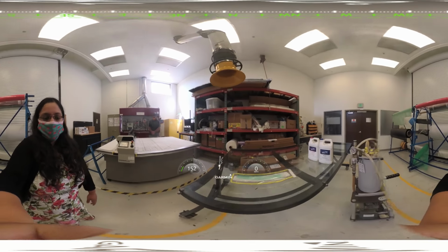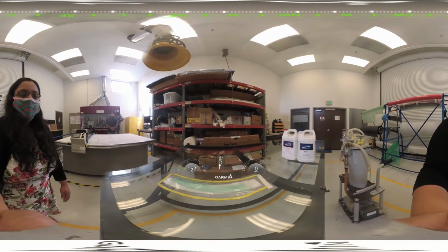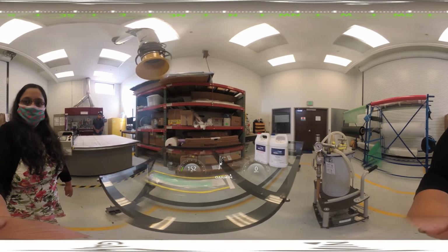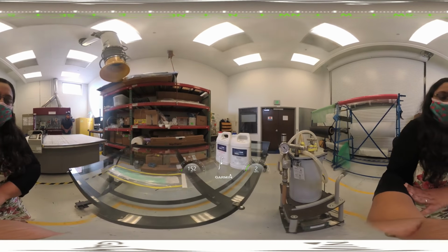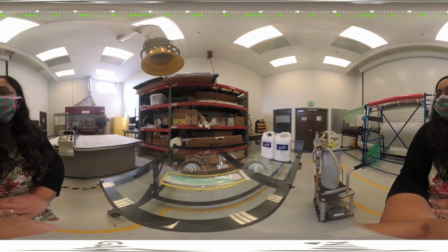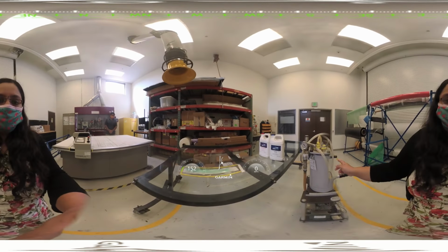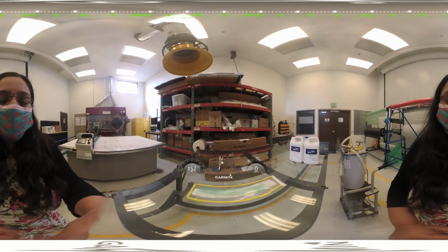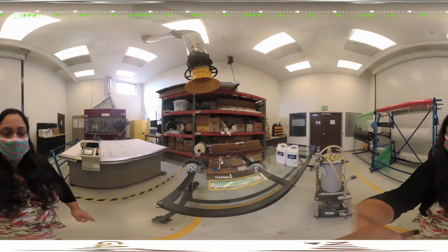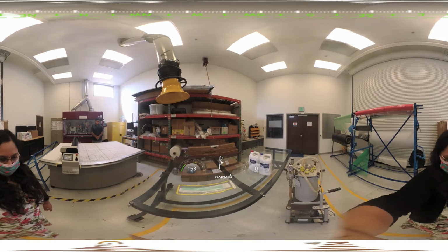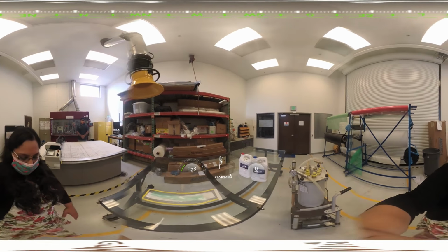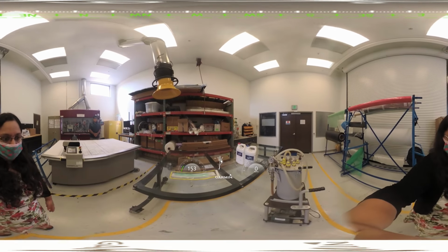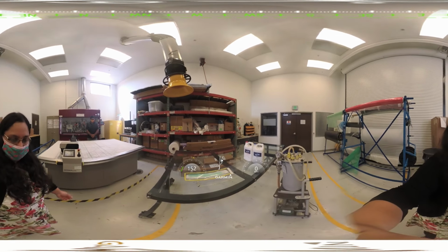And then the fabric is laid up in different number of layers, 6 or 8, and the resin, as you can see, mixed with the hardener, is pulled through the system using the vacuum. So there'll be two ports here which pull the resin and pull the vacuum through. In this method, we are going to be manufacturing the composite and studying the flow of the resin through the system. In the second lab, we are going to do the same with the prepreg.